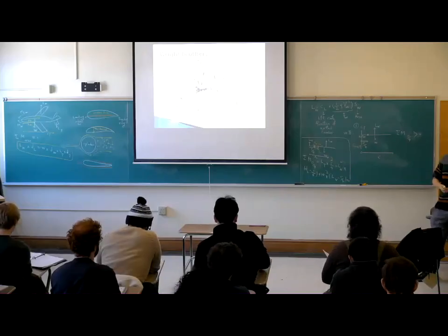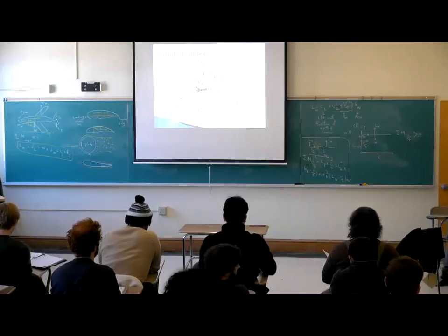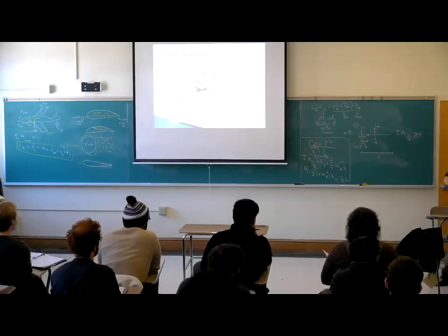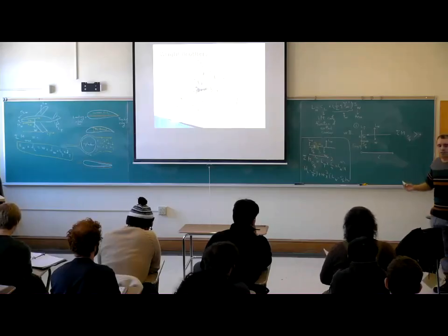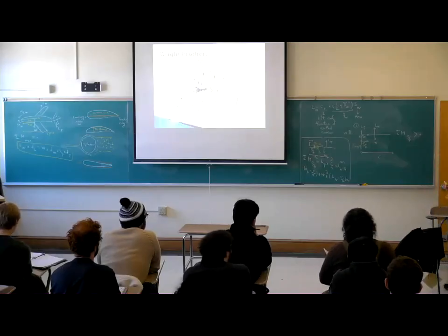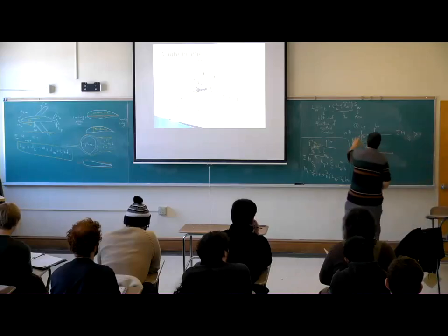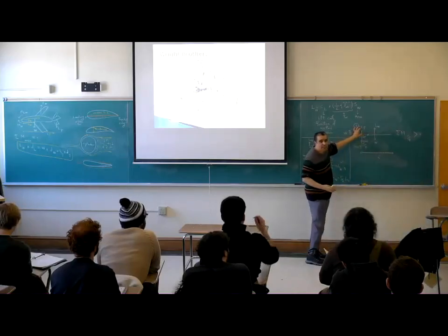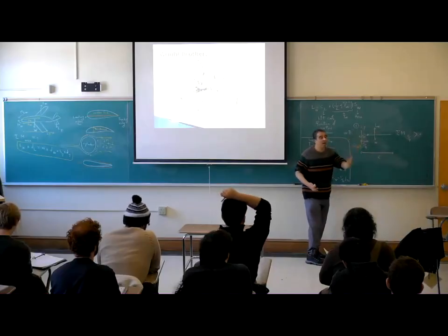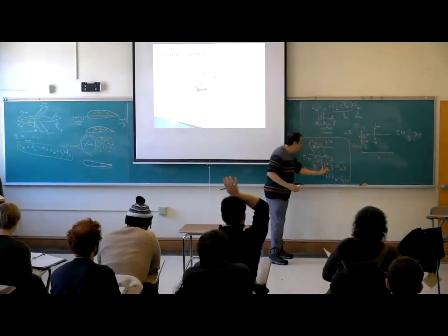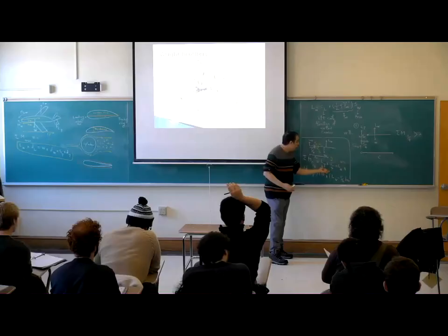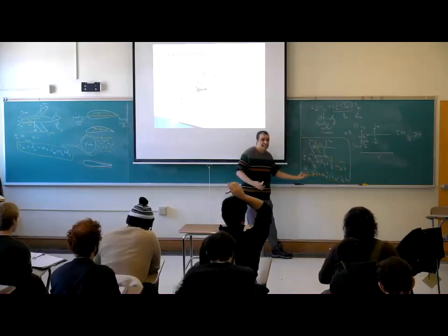Be able to move your tail, the elevator. What should I create to balance this upward gust? Create more lift or drag? More lift from where? The tail. If I create more lift on the tail, my balance is disturbed.